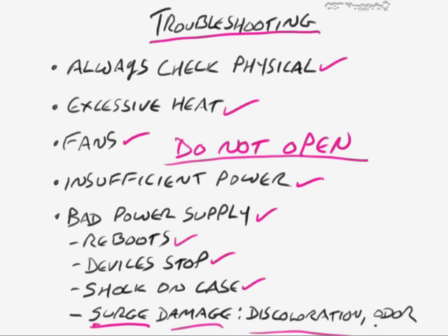Also, check for strange electrical kind of odors. Even on a healthy power supply, it's going to smell kind of electrical. You know what that smells like. But if it's an unusually strong odor, then it may have gotten overheated at some time and needs to be replaced, or it may have started to smoke, and in that case, of course, you need to certainly replace it. So anyway, all of these things are probably going to be very important for A+ exam objectives, so I would definitely be aware of these items.